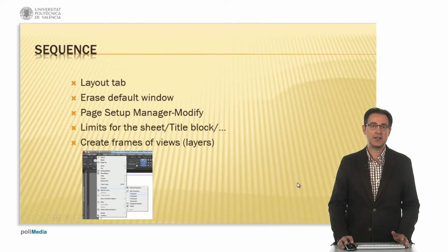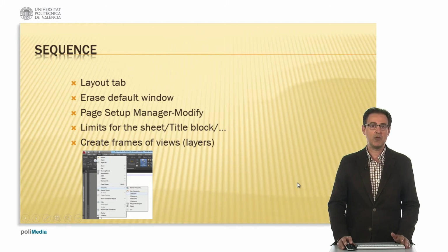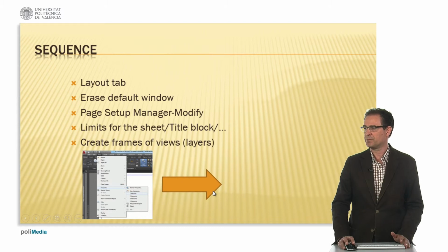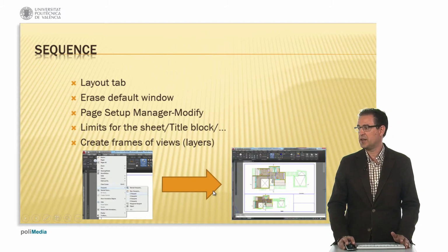You can run this option from the View menu, then Viewports, One Viewport. Here you can see that you have different options for creating viewports: 1, 2, 3, 4 viewports, polygonal and object. We are going to use the most frequent option, that is one viewport, one rectangular viewport. Then you can create as many viewports as you want. Here I have created 2 of them.